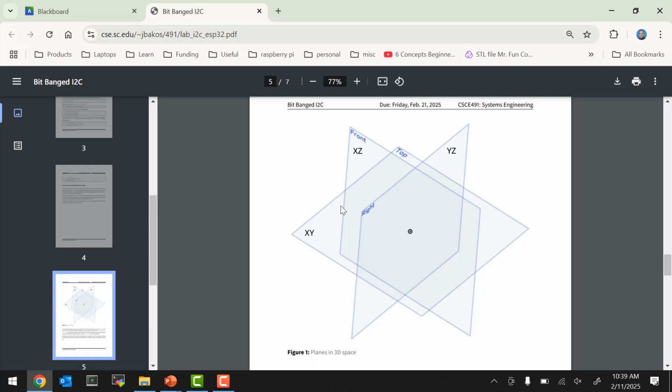And then of course we've got the speaker and the I2C and the LEDs and stuff like that. But most of the pins are taken up by the motors that ultimately we're going to use to try to keep the thing balanced. We're using centrifugal force. So that's the reason why we have to do this. We couldn't tie that pin low on the board because we needed every last pin. Yeah, exactly. Okay. Thank you.